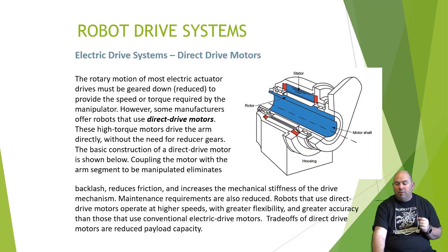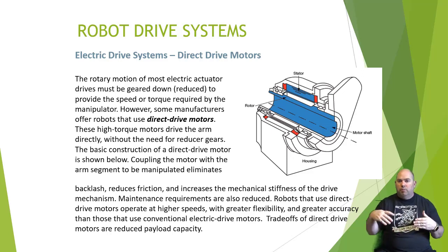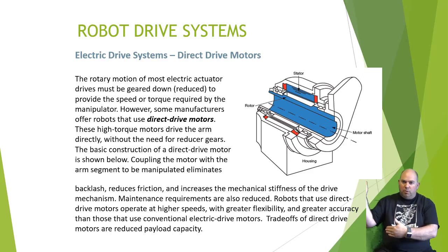And you need to be mindful of the environment. You need to protect it from high temperature, wet, dusty, or explosive environments, things like that. But basically, what we do now with robot systems, we have what we call direct drive motors. So we are putting our motors directly on these joints. So typically, like we talked before about all these rotary joints that we have, or revolute joints. So we're putting a motor directly connected to the joint.